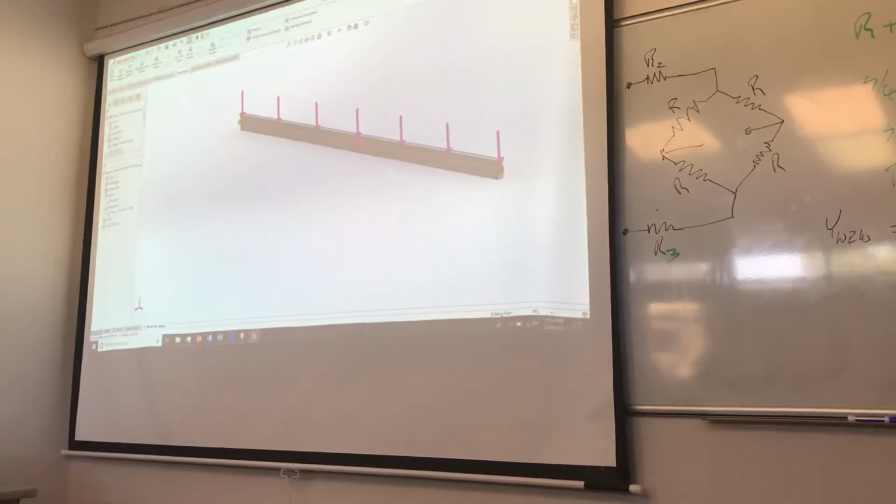Then I'm going to put another load on. My force in this particular case, I get to pick on different things, but I'm going to put it on a joint, this joint right here. I again am going to pick some nice reference geometry like the top plane so I can pick the out of plane direction. I see it again coming up from the bottom because they're stupid about it. So I get my big arrow coming up from the bottom. I want it going down from the top. And I'm going to put about, what, 250 pounds on it? Because it feels good.